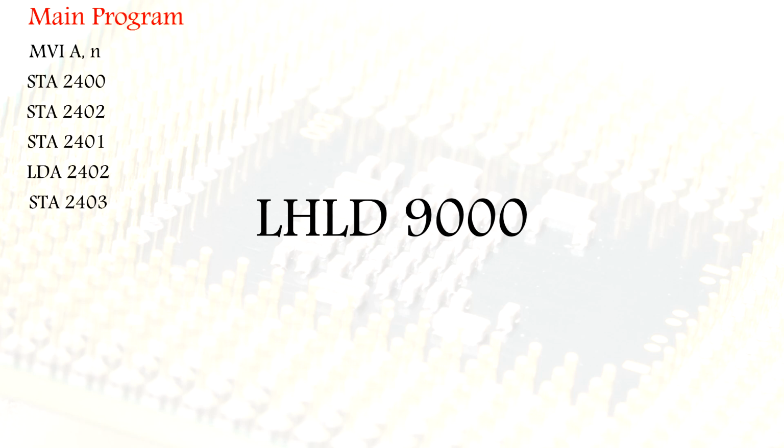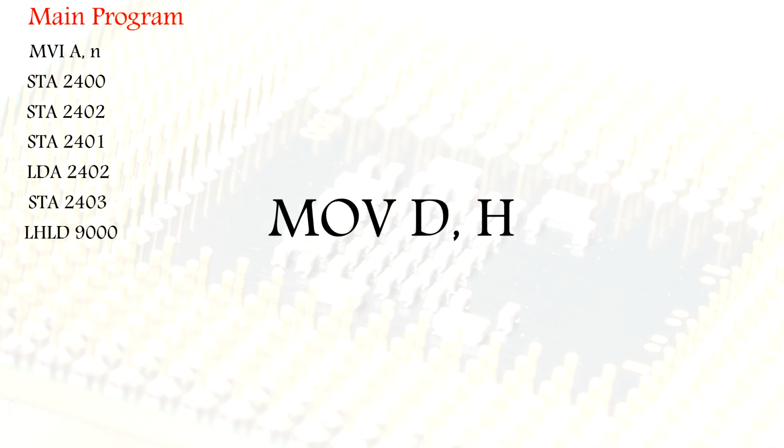So using the instruction LHLD 9000, we are loading the contents of 9000 to L and loading the content of 9001 to H. That means in the H register pair we are moving 4501. So 4501 is actually the address where matrix B is stored in memory.